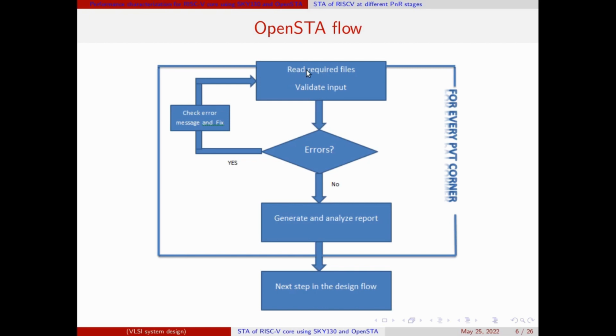After providing the input to the OpenSTA tool and running the STA, we check whether an error is there. If an error is there, we check the error message, fix it, and rerun it.